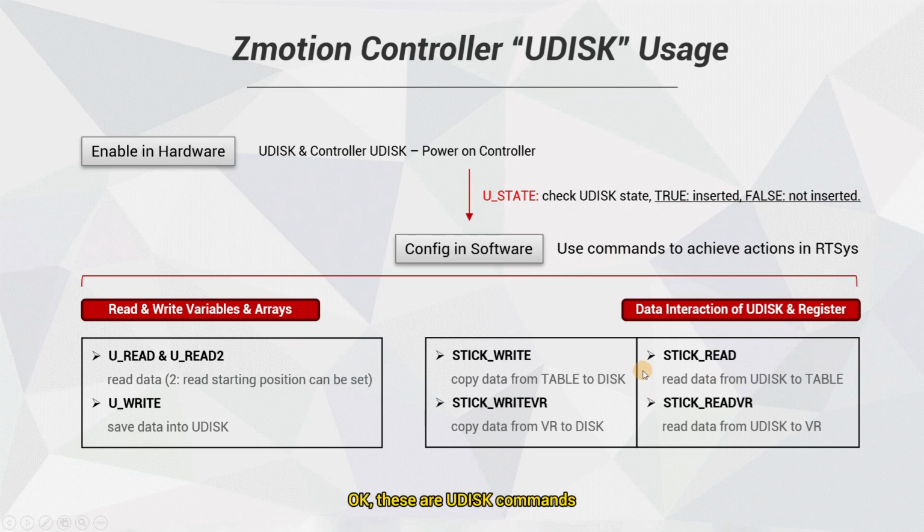Okay, these are the UDISK commands. UState, you can know the state according to the returned information. These three are for reading and writing variables and arrays. Obviously, this one reads data from UDISK to variables or arrays. This one saves data into UDISK.